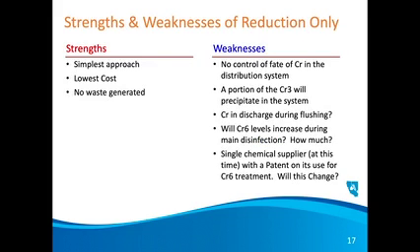It's obviously the simplest approach, lowest cost, no waste generated, because you're just adding a chemical. It's almost like the concept of using a sequestering agent for manganese treatment in wells, and just not letting it precipitate out in the system, and just putting it through.